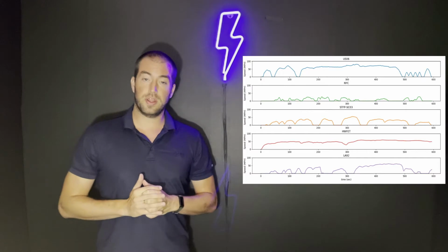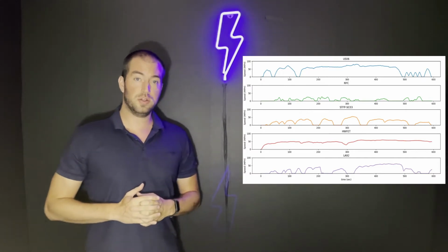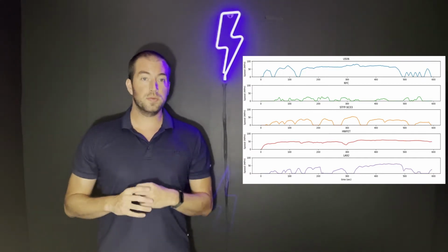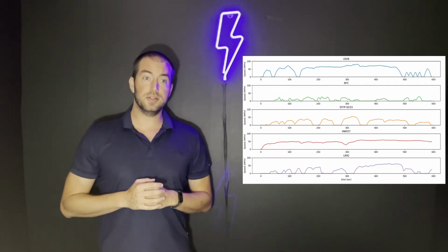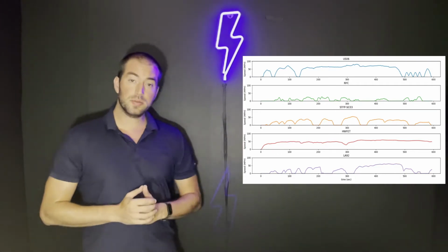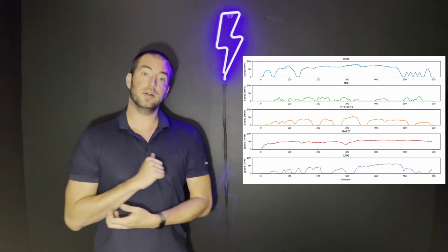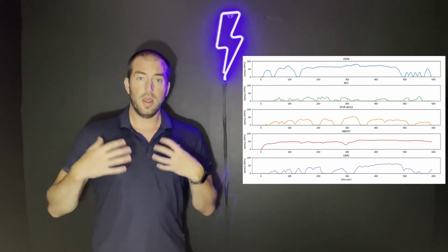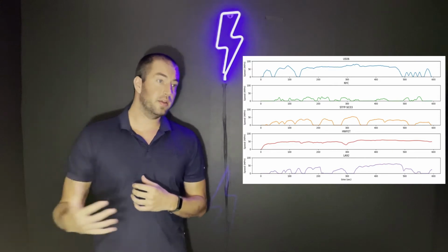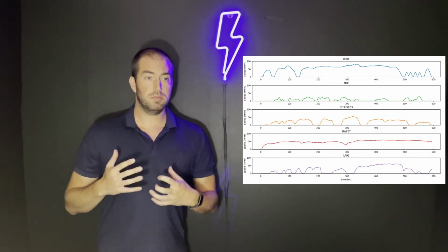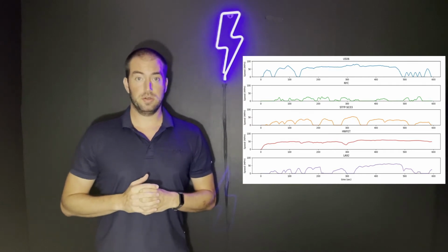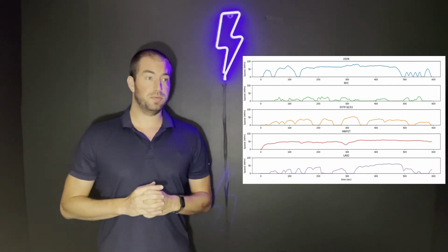Now this is for certification, and when we're measuring for certification, we're going to take one measurement on the DC bus. So we're going to instrument the current and voltage of the DC bus. We're going to look at power consumption throughout the drive cycles, and we're not only going to look at power, but also calculate energy from it. This presents a very interesting measurement challenge because the accuracy of this measurement really matters.